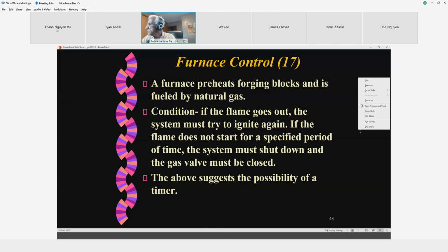Then magically or some disaster, the flame went down after it came up. So the controller says, oh, there is no flame. The flame went down. Come back again and ignite. Okay? Keep the gas valve open. When the gas valve is open, obviously gas supply is coming. So all this is happening very fast. So if it is successful the second time and the flame sustains, ignition has no role. The moment flame arrives, ignition should go.